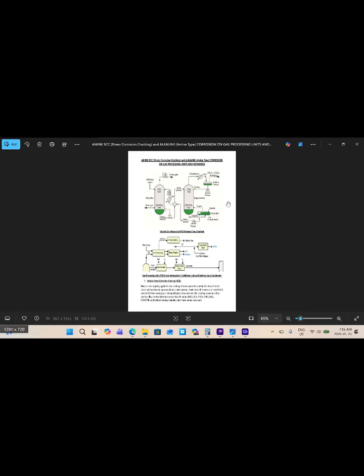amine. Again, by the reboiler and heating, all that H2S and CO2 is removed from the rich amine to make it lean amine, and the lean amine is recirculated. This is a closed loop system, regenerating the lean amine again by removing the H2S and CO2. Finally, the H2S and CO2 go to acid gas service for extraction and safely remove those toxic gases from the service.